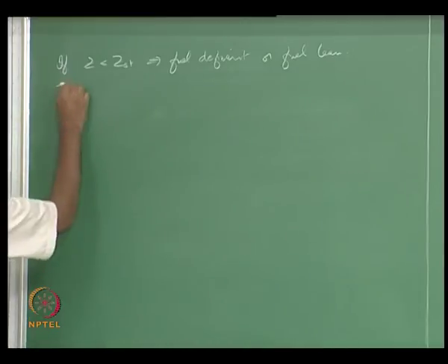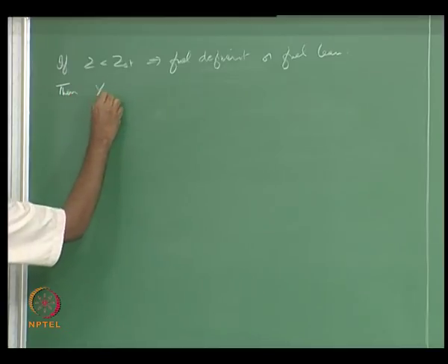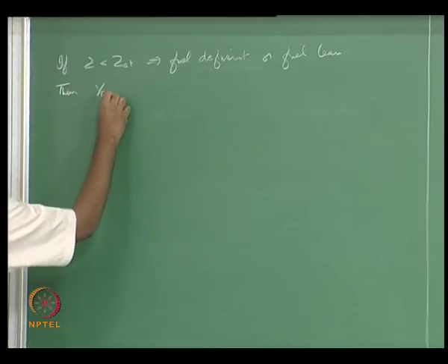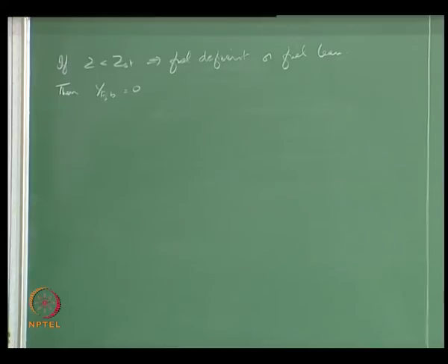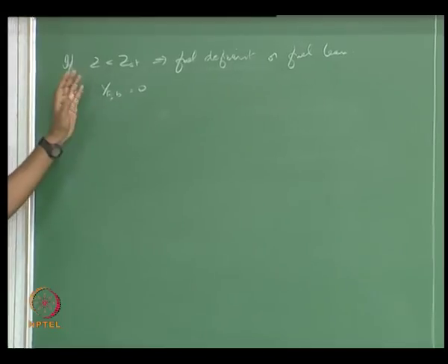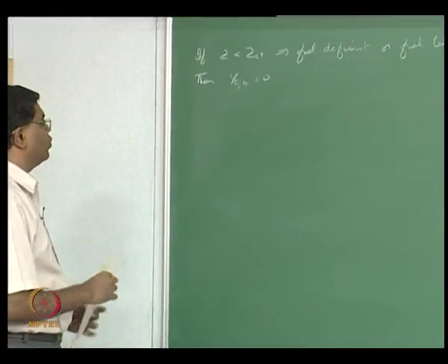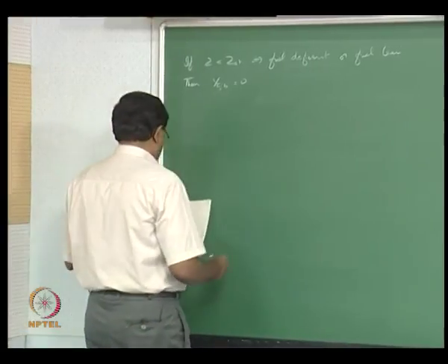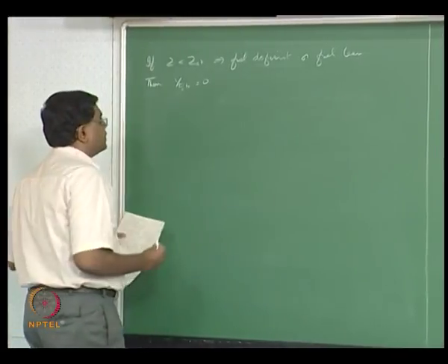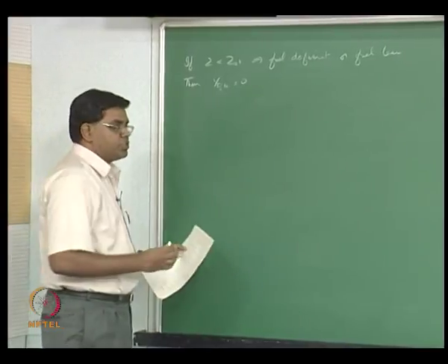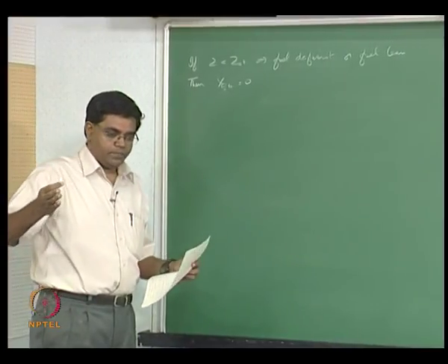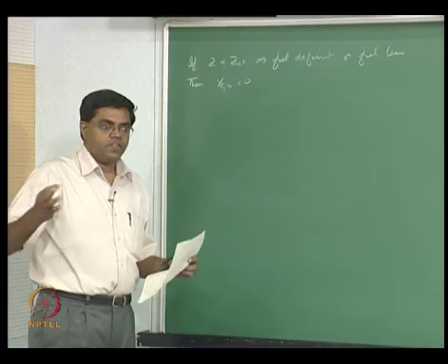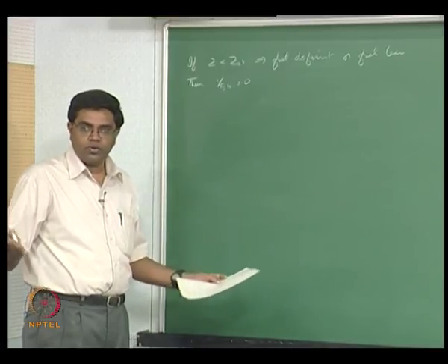Then YF burnt is going to be 0. This is now the mass fraction of fuel in the burnt products. So you're not going to have any excess fuel in the products. Therefore, you can now substitute YFB equal to 0, which terminates the combustion, right. So the combustion essentially doesn't proceed simply because you run out of fuel. You don't have any more fuel.